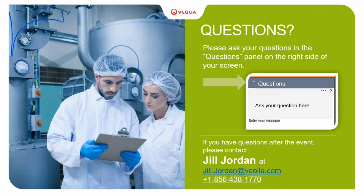So what we've actually done, we will seed lagoons and CSTRs with granular sludge, and we'll chew it up to make it flock, or just let it naturally turn into flock because of what it's being fed, because we can transfer a lot more kilograms of sludge in the granular form than we can in the flock form. So therefore the transportation costs would be much less.